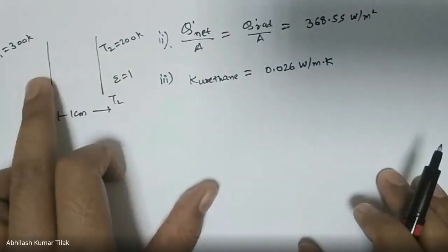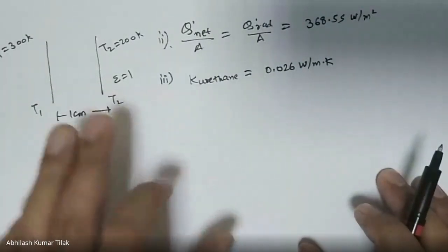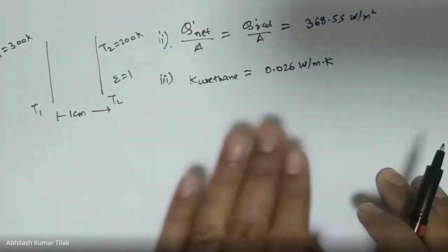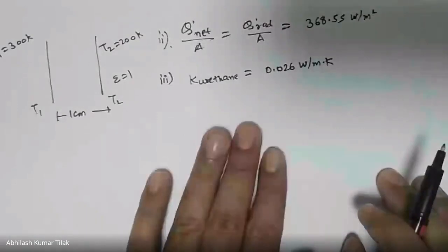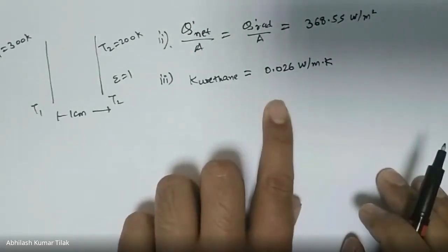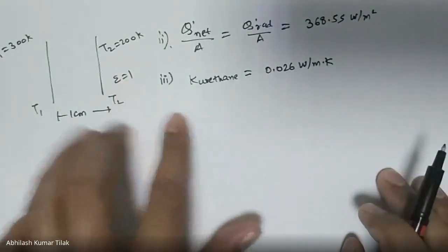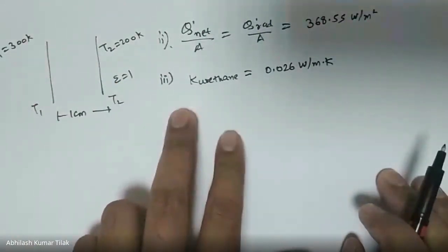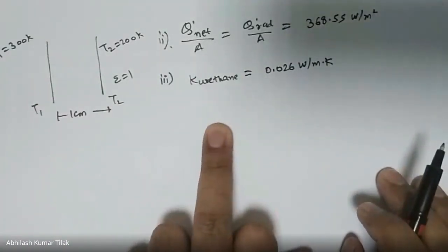There is an insulation between these two plates. So either it will be Q conduction or Q radiation. The Q radiation is already accounted in the value of the thermal conductivity of urethane, which is placed between the two plates. So if we are calculating the heat transfer through this insulation, we have to consider only the conduction part.